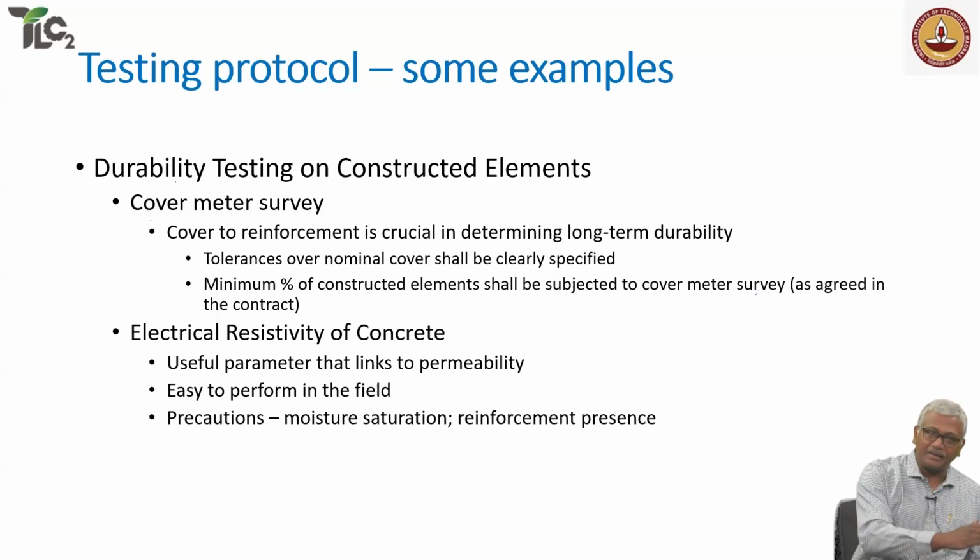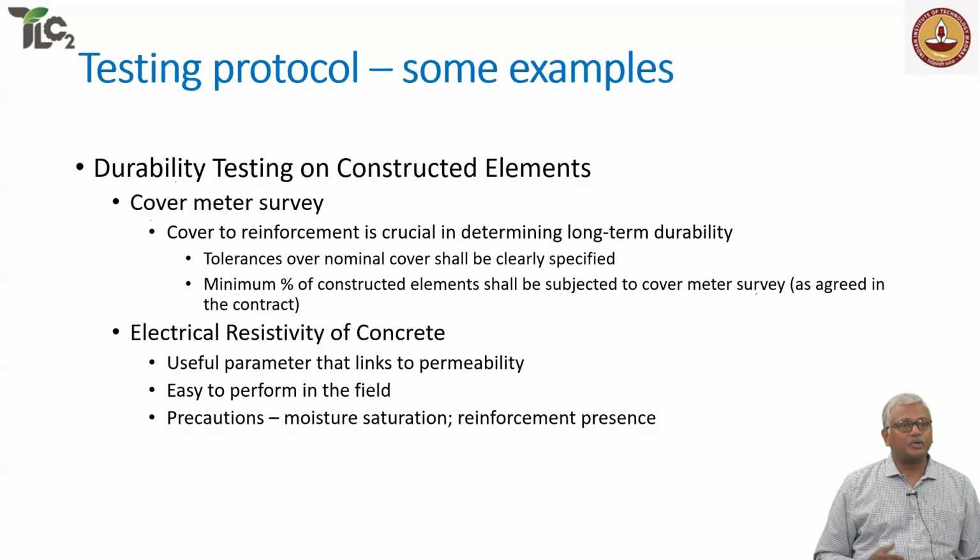If it's been more than 10 millimeters away from the target, then you know there's a problem. People have not done their job properly. Okay. So all of that can be assessed. It's not going to be just relying on the kind of blocks that we use during the preparation process. Now, tolerances should be clearly specified in the specification. Is 10 millimeters acceptable, or should it be 5 millimeters? That is something that needs to be brought into the specification.